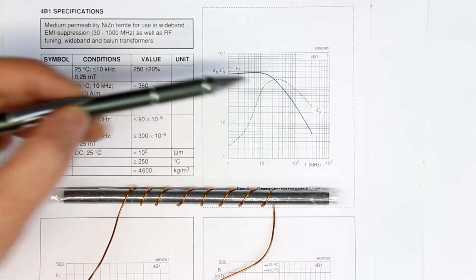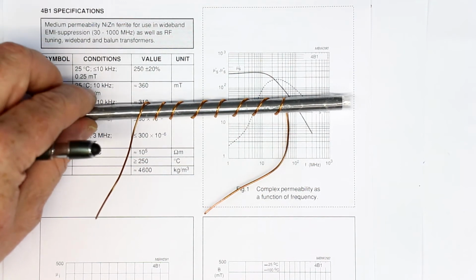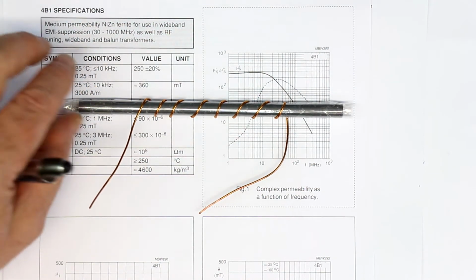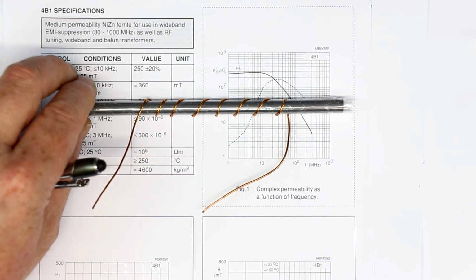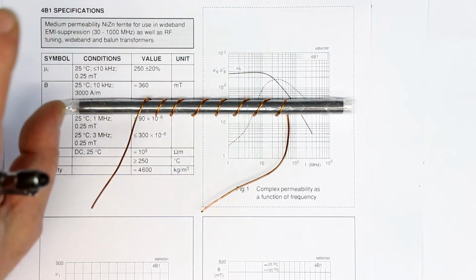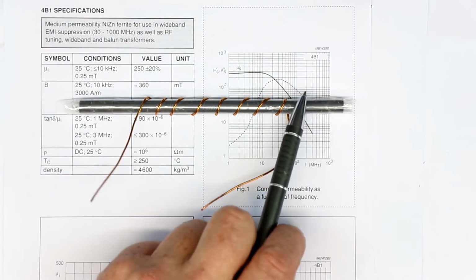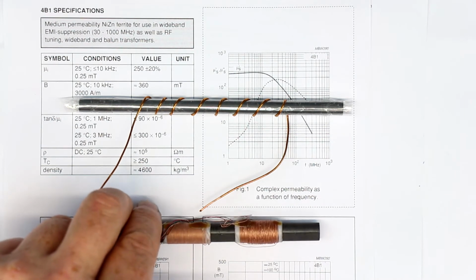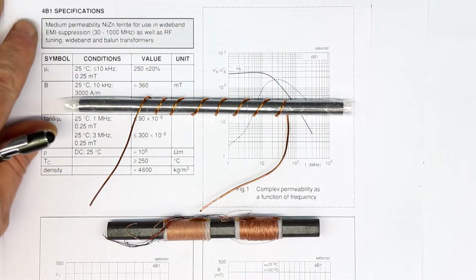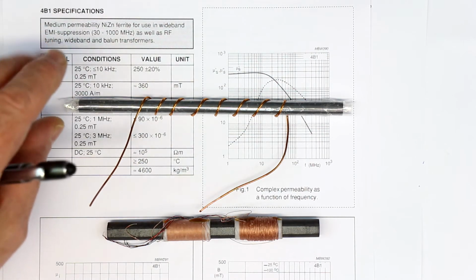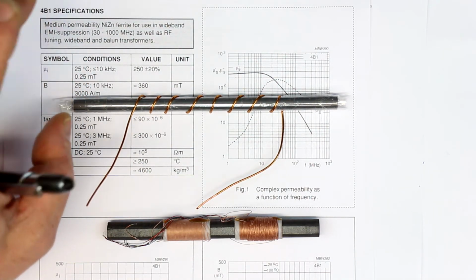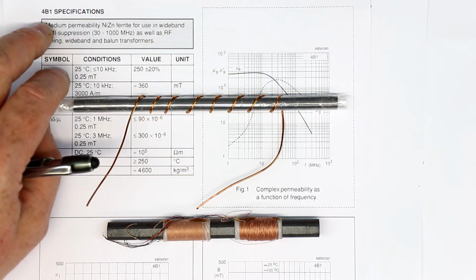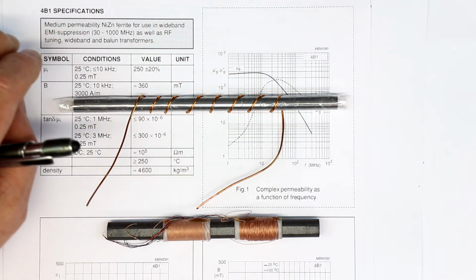The absolute maximum that you can use this material is perhaps 10 megahertz, but I would not try to use it with the expectation of a high Q factor above 5 megahertz. So anyway, ferrite-rod antennas are quite difficult, and we really get to the limit of what our spreadsheet can do for us. So let's make 2 or 3 experiments still and then go over to our spreadsheet.